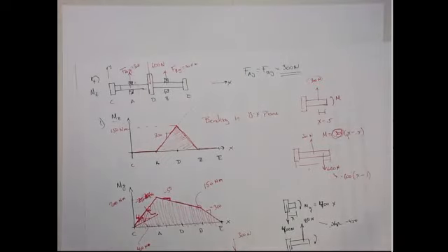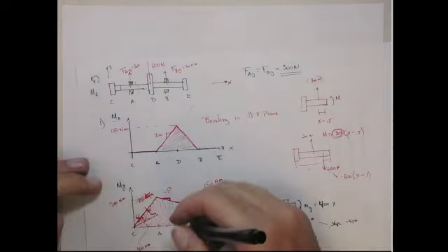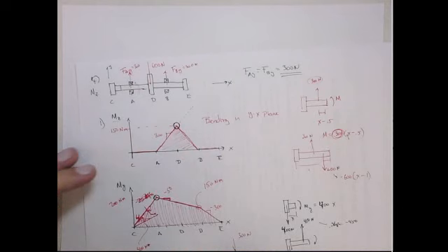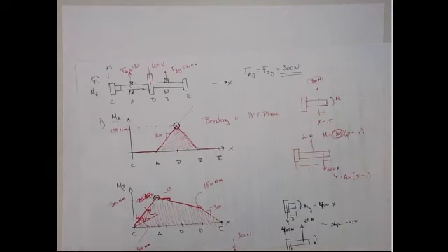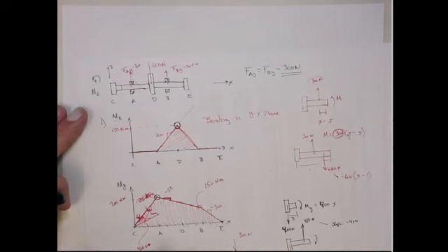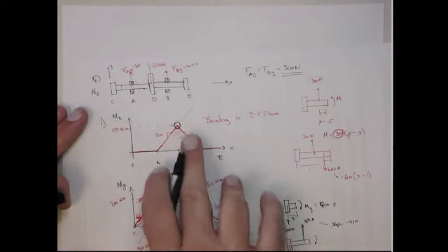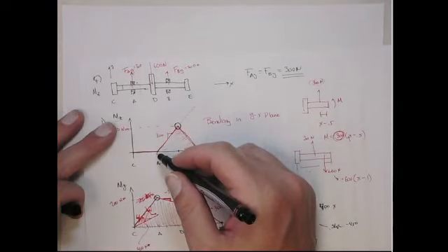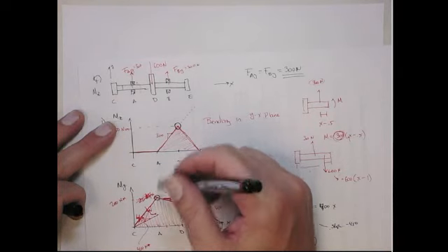Where are the maximum stresses going to occur? Well, there's really 2 points. We have to be worried about point D and also point A. Although the absolute maximum value we have here occurs at point A. At point A, you have the 200 Newton meter bending moment, which is the biggest thing on this whole diagram. D only has a value of 150. But if you look at the other mode, in the other plane where this is 200, this is 0.